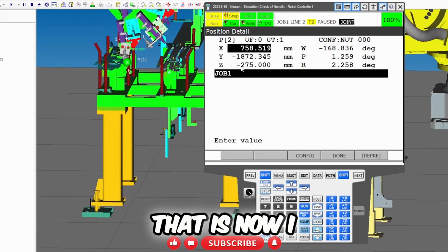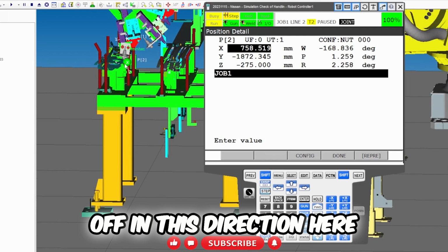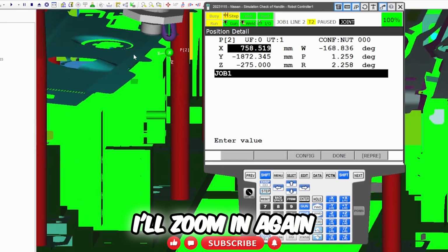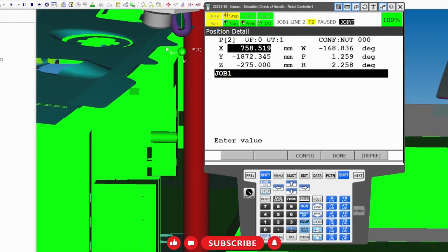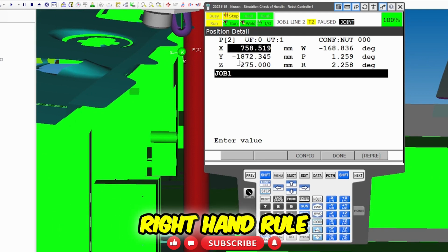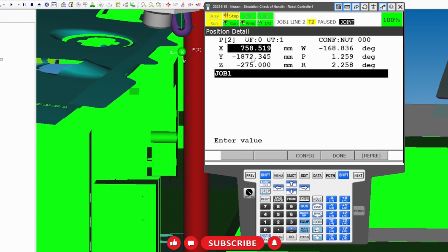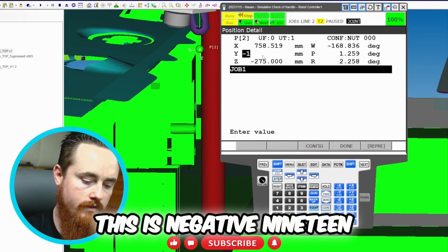The reason for that is I notice the robot is off in this direction here. So I know that if this is positive and I need to go over some more, I'll zoom in again. I'll see, okay, how many millimeters do you think this is? Maybe 50 or 75 millimeters, okay? So going with my right-hand rule, that means positive is this way. So I need to go in the negative direction towards the part. So with that being said, if I need to go in the negative direction, let's say 75 millimeters, I'll just also say with rough positioning, this is negative 1950.